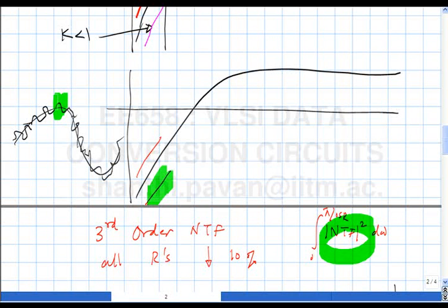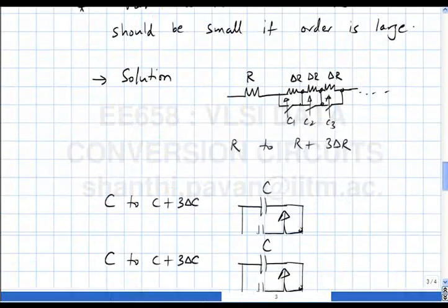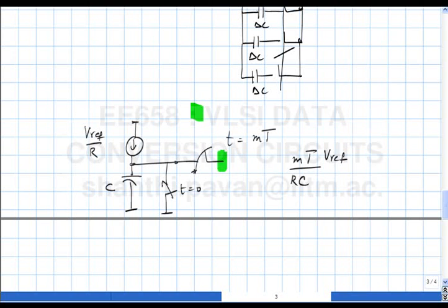In any case, RC time constant calibration is still a research area, in the sense that a lot of people are trying to do it without adding too much extra hardware. Any technique like this basically adds hardware: extra resistors, extra capacitors, some measurement, and so on. If something could be obtained directly from the sigma delta itself without doing anything extra, that would be a nice thing.